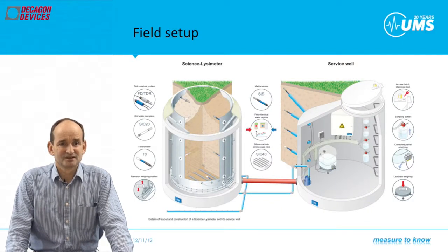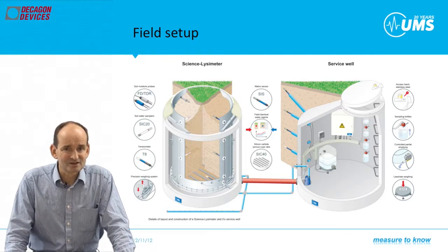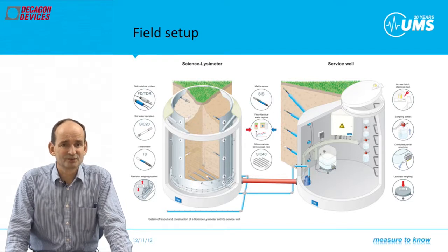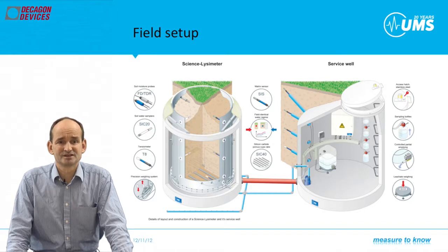Special here is the lysimeter vessel made of stainless steel, with watertight sensor ports which allow the soil to move inside the lysimeter ±10 mm, sensors. The Smart Field Lysimeter has 3 ECO-TM probes for the water content and the water temperature. Further, it is equipped with 3 MPS2 sensors for measuring the matrix potentials.